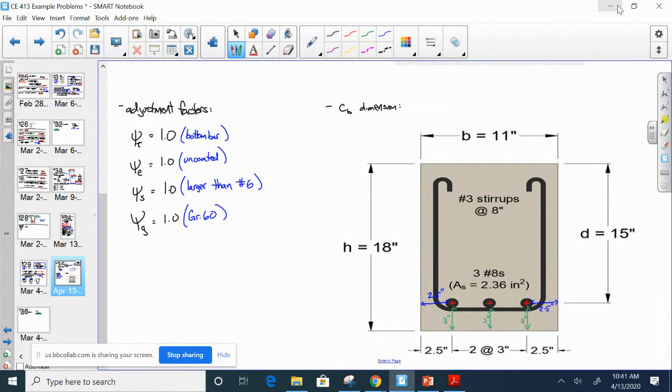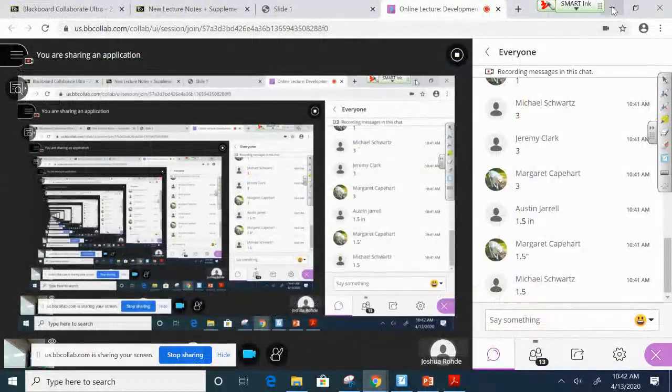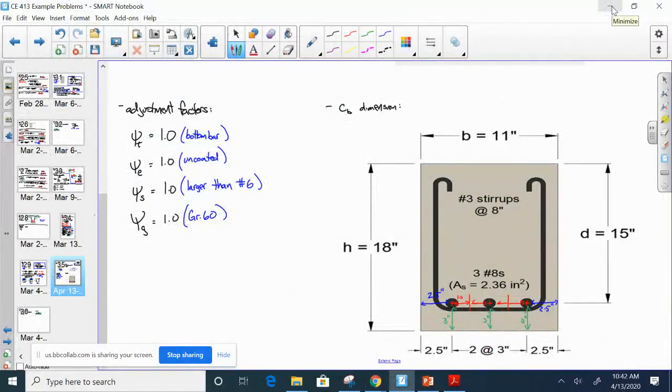And then the last thing you have to do is you have to figure out how far it is halfway over to the next bar. So we're talking about these dimensions here. They're all the same. And what are those dimensions? Again, it's halfway over to the next bar, not the whole distance, but half the distance. There you go, exactly right. So this is 1.5 inches, 1.5 inches.